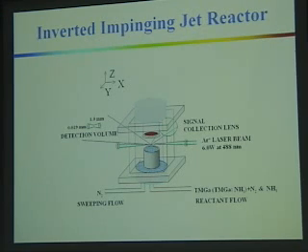By looking at the rotational spectra of our carrier gas, we can also estimate quite accurately, within about 10 degrees, the temperature locally. This whole reactor is mounted on an XYZ stage, so we can actually move the reactor and sample different positions. So with a heated susceptor and an impinging flow, we're able to measure the center line composition and temperature profile, from which then we can look at the species present and back out rate constants and try to understand the chemistry.